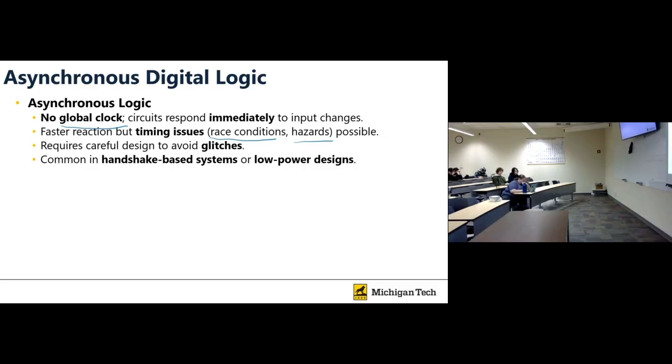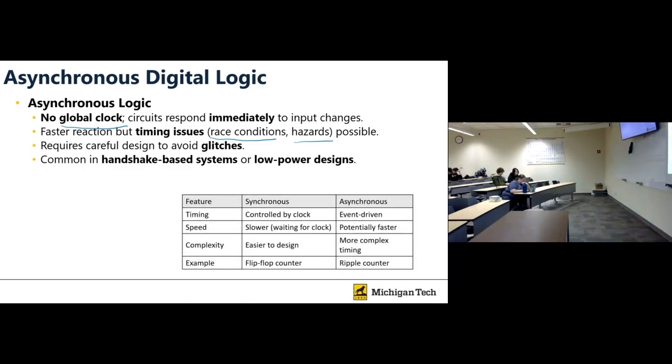So that's the type of system that doesn't need to be synchronized by time, but synchronized by acknowledgements. You have a request and acknowledgement. So, I want to use memory, so memory gets turned on, like when you click on your keyboard, it starts working. When you are not using it, it's not synchronizing with the clock and not wasting energy. This type of system is called an asynchronous system. The timing is not controlled by a clock; it's event-driven.